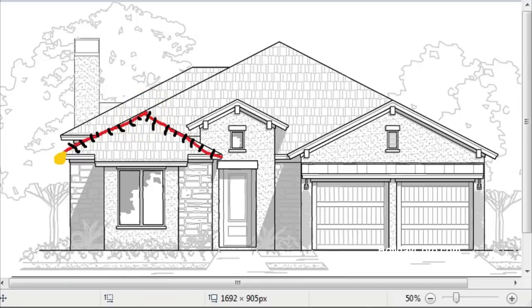Now, let's go ahead and finish out this diagram if we were using pixels. So we'll go ahead, run pixels up here, and let's say that even though we would like to just go ahead and just roll this around and continue on down as one continuous string, often there are power limits, so we're going to stop, and we're going to go down here, and again, let's say that that's as long as we can go, and we'll start over again here. So in this particular case, we would have a pixel controller here, a pixel controller here, and let's say a pixel controller here to hold this section here.